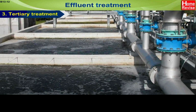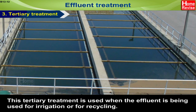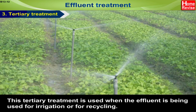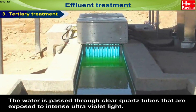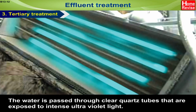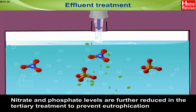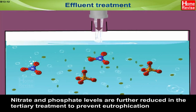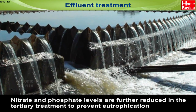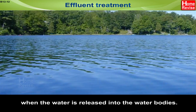Now number 3, tertiary treatment. This tertiary treatment is used when the effluent is being used for irrigation or for recycling. The water is passed through clear quartz tubes that are exposed to intense ultraviolet light. All pathogens are thus fully destroyed. Nitrate and phosphate levels are further reduced in the tertiary treatment to prevent eutrophication when the water is released into the water bodies.